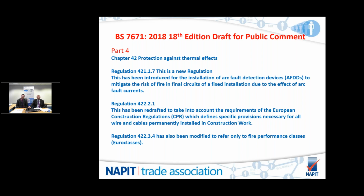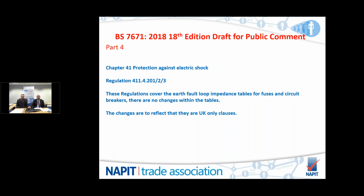The next regulation, 422.2.1, has been redrafted to take into account the new requirements of the European Construction Products Regulation for cables, CPR, which defines provisions necessary for cables and wires that are installed permanently within construction work, so fixed installations. And it refers to the next regulation, 422.3.4, which has also been modified to refer only to fire performance classes of Euroclass cables.